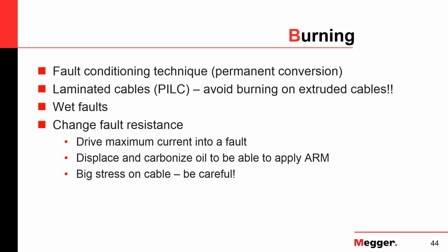It is not for plastic cables. On plastic cables, it is really your last stand, because it can actually really harm your cable. It will heat up your cable, and a large amount of current that is also there for a long amount of time can actually melt the insulation at a certain point, and then your concentric is actually trying to slowly wander towards the conductor. And if you're lucky, you create a situation where your TDR can pick it up, or where you have the chance of thumping. But where do you stop? You don't know where to stop.